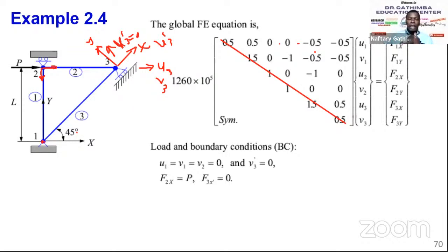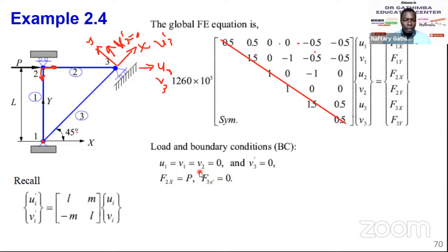So it means at the support, when there is no load applied, what we calculate is the reaction. But because of the roller support there, we know the reaction is equal to 0. It could have been 0 on this node, but because there is a force applied here, we already know what force is applied at that node. But in this direction, the local coordinate system at node 3, we know F3x is equal to 0 because of the roller support.